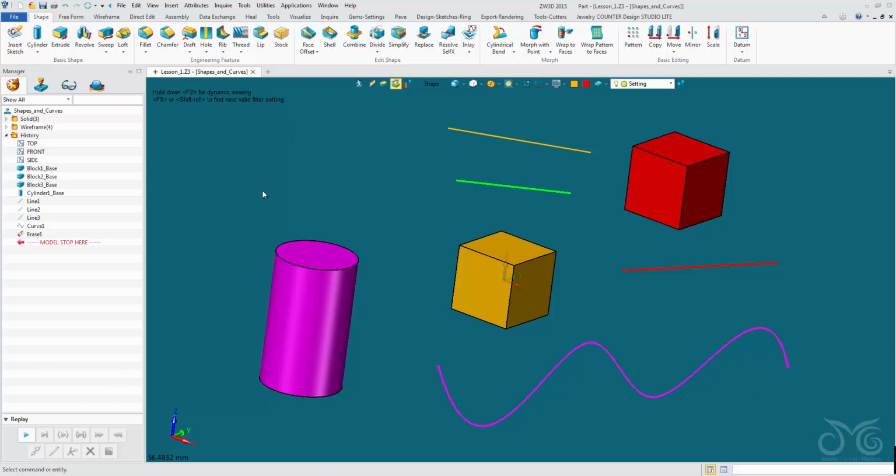and this is erased. We need an erase instead of just a delete, because we may want to use an operation and then get rid of it when it has served its purpose. For example, we may have brought in this block simply as a reference. Once we have taken our reference from it, we may want to erase it from our 3D environment to tidy up our workspace, and that is where the erase comes in. We do not want to delete it because we need it as a reference point somewhere in our history, so we can simply erase it when it has served its purpose. So this is the difference between an erase and a delete.